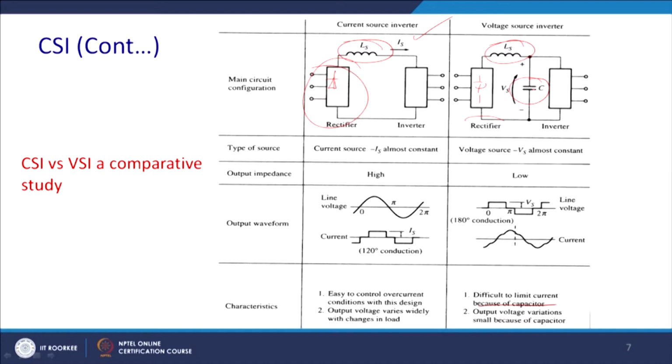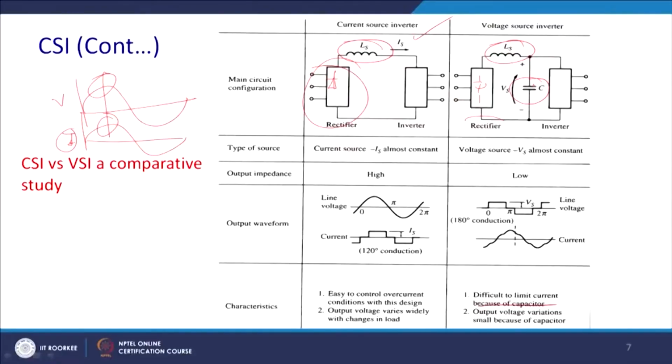Why? Because it is a two task. Please understand that even if it is feeding a resistive load, this is a voltage and this is a current. Even though you have given a constant voltage and you are converting it into AC, you are fetching maximum power, that leads to discharge of this, somewhere this energy will come from, and this will be fed from this capacitor.